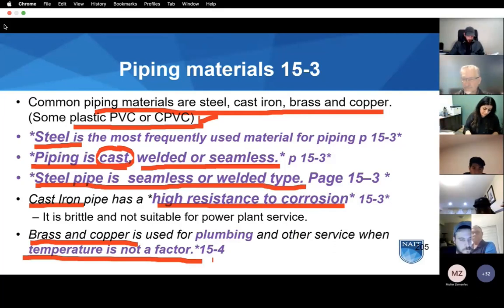And the other thing is, if you work in an ammonia plant and you have exposed copper, the ammonia from the random leaks that occur from time to time in an ammonia plant will destroy the copper in very short order. So copper and ammonia are reactive, and very rarely is copper used anymore in industrial settings. We've switched it all over to stainless steel.